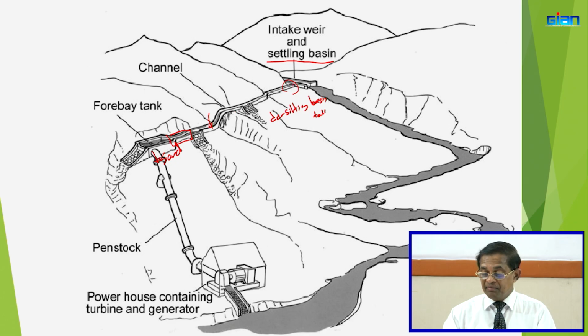What happens is, when silt enters here, it gets deposited at the bottom of the canal, because the canal flow rate is not very high, it is a very slow slope. Therefore, over time silt fills, and then the canal height shortens, and the water cannot flow now, right. Therefore, it is important that no silt accumulates in the canal.